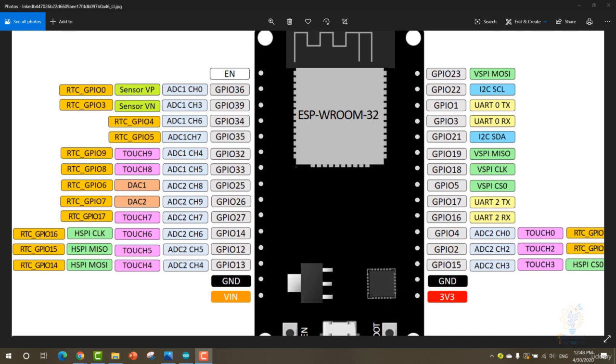We will use a value of 5000 Hz. That works fine with our LED. We must also specify the LED PWM channel and the resolution of the PWM duty cycle. I won't explain PWM, because you must have some basic knowledge about PWM signals, but what it takes is a resolution, a channel, and a frequency. So after specifying the duty cycle using the resolution, the frequency and the channel, we can start programming.